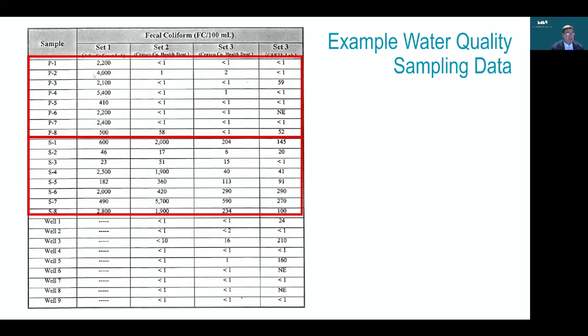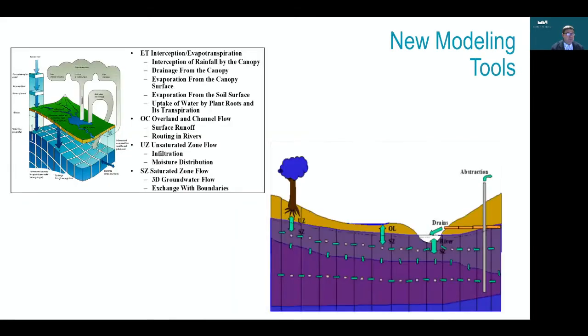So what you can see is there seem to be some issues with the first set, some contamination issues from the person who was doing the test. But if you look at these next three, at the same location at the same time, the groundwater sample had fecal coliform counts less than 1, whereas surface water counts could be in the hundreds to thousands, getting close to 10,000. The measurements here are for wells located at the natural area that we ultimately helped the town get a grant to purchase, that we ultimately are pumping water to.